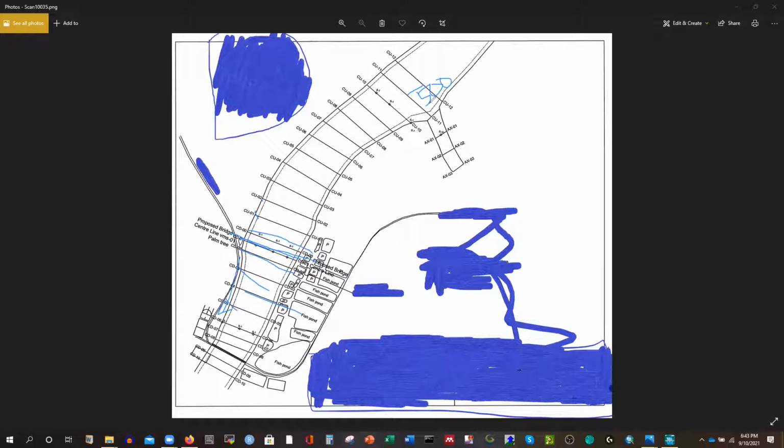But in the model, you can import the cross sections, or you can create the cross sections from upstream to downstream. We'll start the cross sections from upstream to downstream, and the upstream cross section number will be the higher number, and the downstream cross section number will be lower. That will automatically be fixed. If you provide two numbers, 1 and 2, then 1 will be the downstream and 2 will be upstream. That is the notation. The modeling software HEC-RAS will automatically understand that the minimum value is the downstream cross section, and the maximum value is the most upstream cross section.